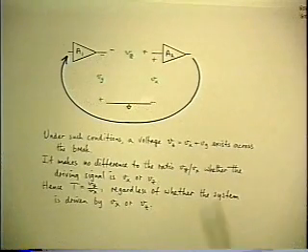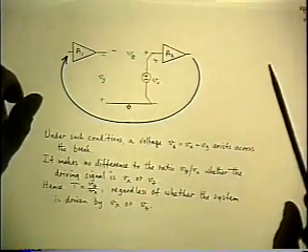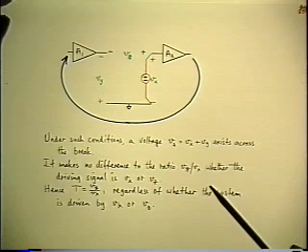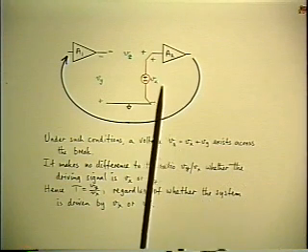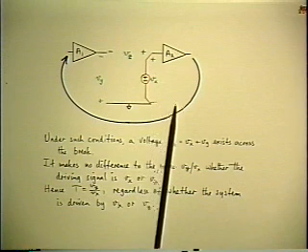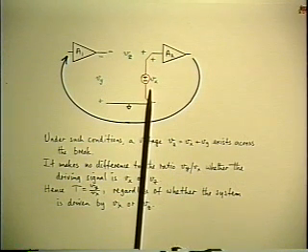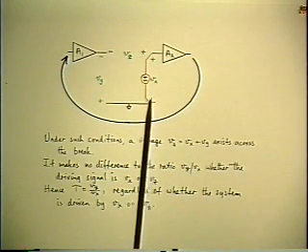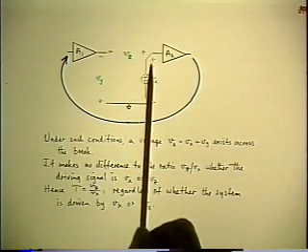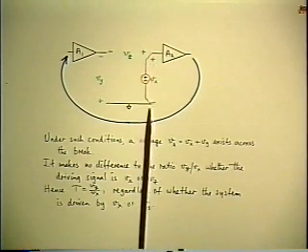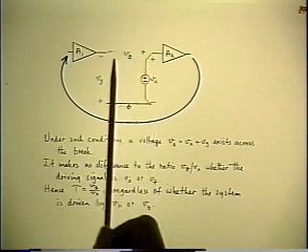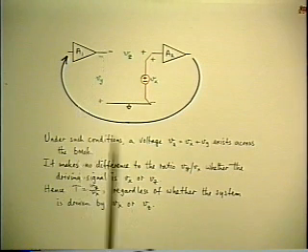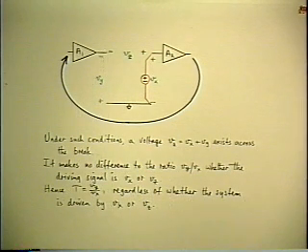Here's the same thing again. There's our independent source, assuming that in practice we have reestablished the operating point. Okay, here's my signal generator, and just to make things concrete, let's assume that it's 1 millivolt AC at 1 kilohertz or whatever. I can take a voltmeter and hang it across the same point and measure that 1 millivolt. I take the voltmeter and move it over and measure Vy, and suppose it reads 10 millivolts. Then the loop gain is 10 at that frequency.